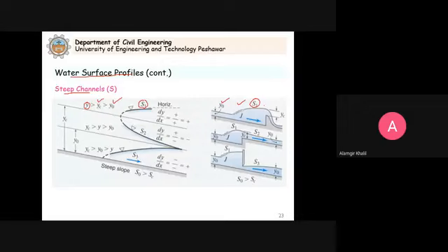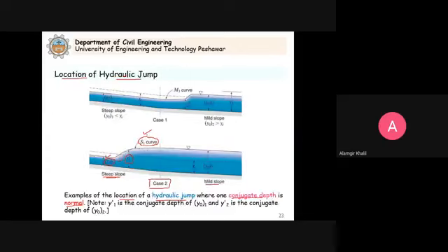If it has to occur, it means it is an increasing slope. This S1 is increasing, that's why dy by dx is positive. So now if I come back here, if we say that we have an S1 curve, it means that this curve will increase. As you can see here, it is increasing and it is further expected to increase here. Now when it crosses the break in the slope, this is the break in the slope, the slope becomes a mild slope.